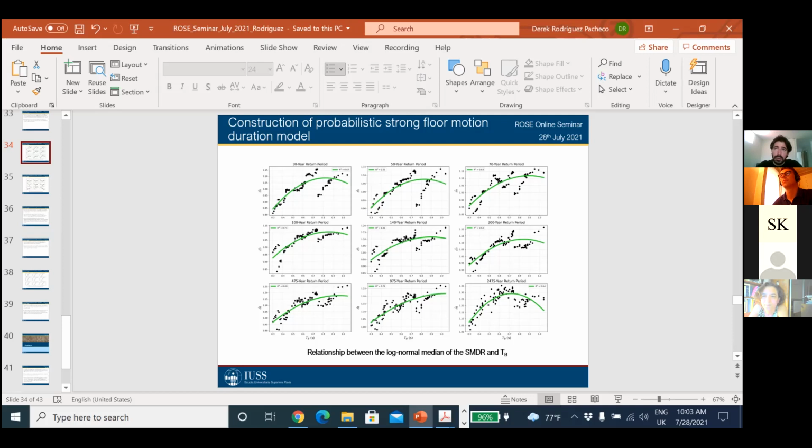This is a big issue, and one of the things I mentioned at the beginning of the presentation as well, is that with non-structural elements, the archetypes are much more variable than the ones for structural systems. As you were saying, the geometric characteristics of piping, for example, are very different from those of a partition wall or mechanical equipment or whatever. However, most of them have a common characteristic, and that is that they are usually anchored to the structure.